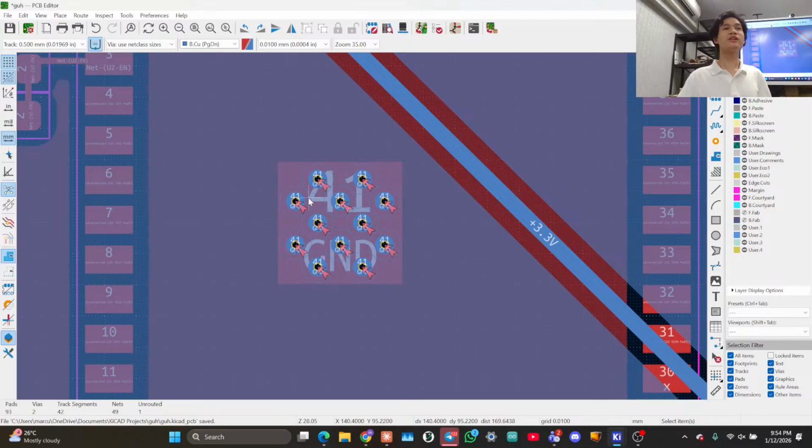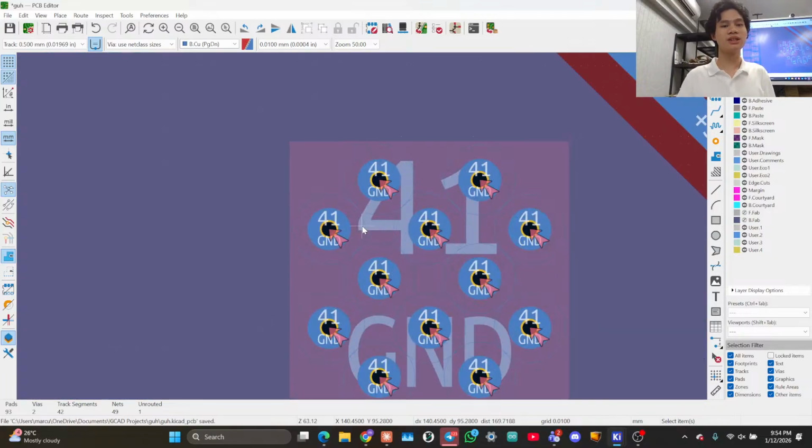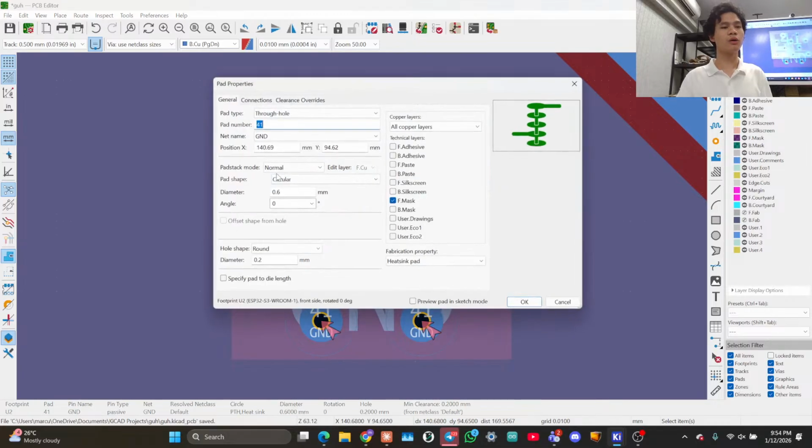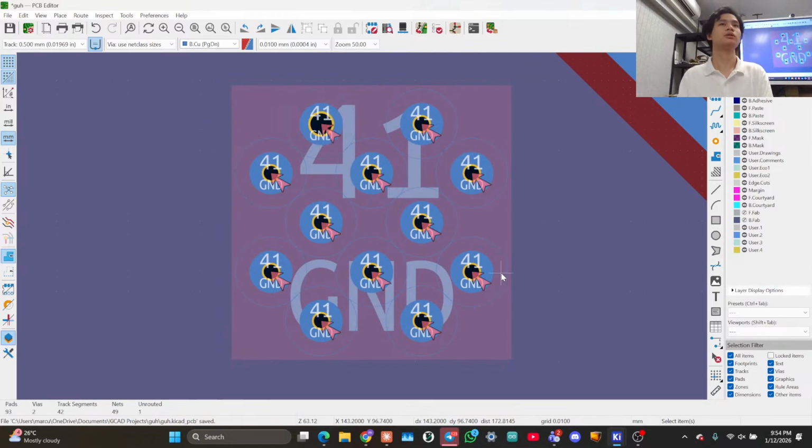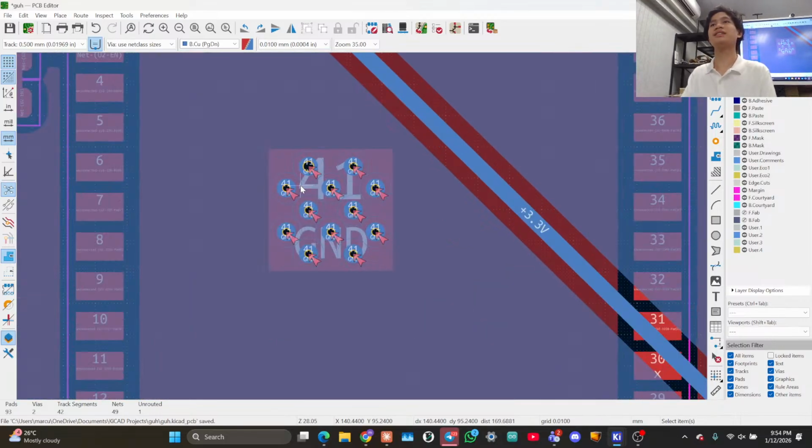So when we put vias specifically to conduct heat, we call them thermal vias. Electrically they work exactly the same as regular vias. We're just using them for a different reason. Okay, so these are thermal vias, and in this case they're all too small, so the diameter should be 0.3 whatever. Smaller vias are more expensive to produce. 0.3 is the standard, 0.2 is expensive.